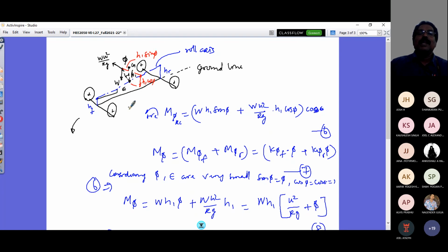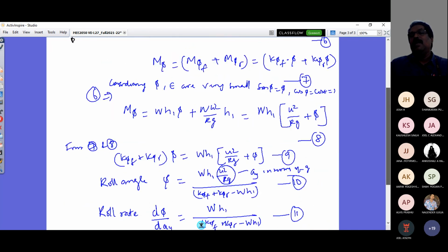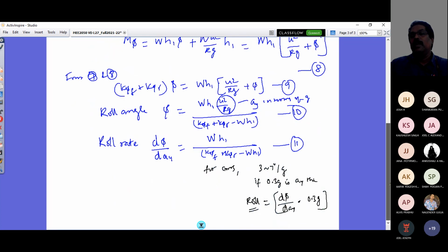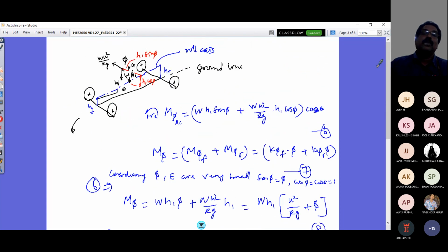But you understand the significance, or the need, of roll moment distribution is because real vehicles do have roll stiffness of their suspension, whereas the bicycle model doesn't account for the suspension. However, that model was quite a good model for steady state motion and steady state understeer gradient and so on. We have looked at it, right? So with that note, I'll stop today's class at this point of time, and then again we will look at it in the next class.